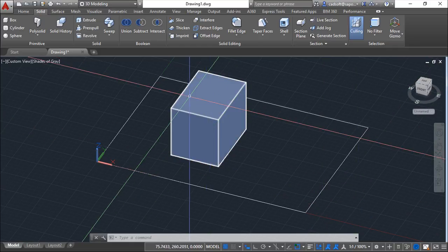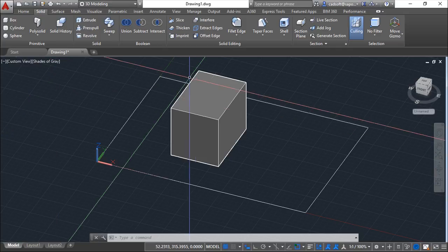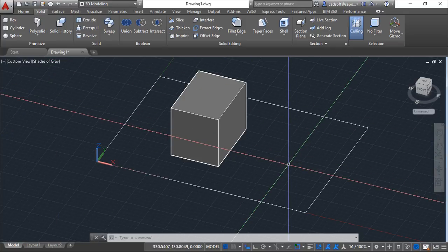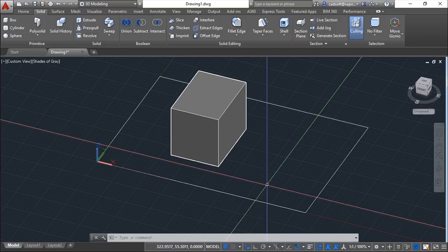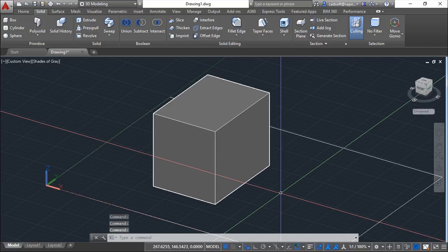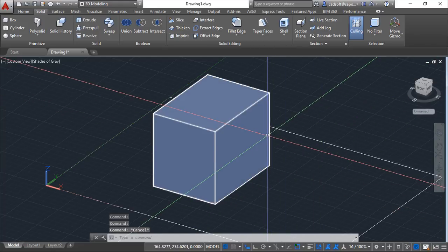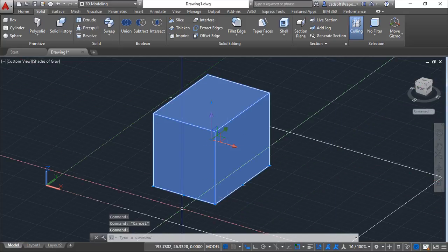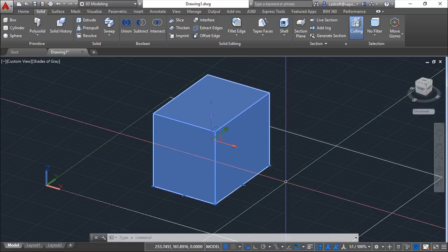Besides this primitive, this solid, you have others like the cylinder and the sphere. These are very simple solids, so I don't think it's very important because they are very easy to build. Then you have the possibility also, we've seen the grips in 2D, and the idea of the grips was that when you click one object after creation, you had these symbols that allow you to edit the solid.